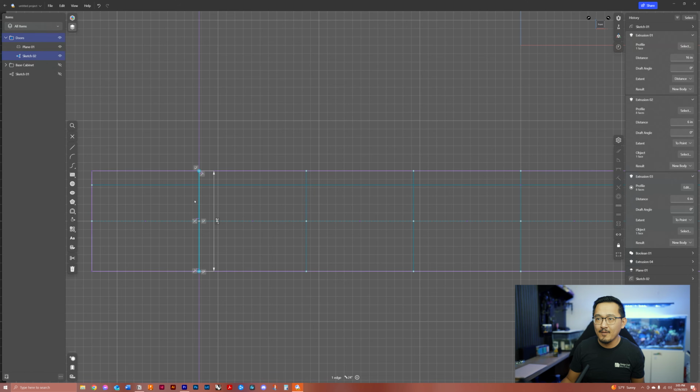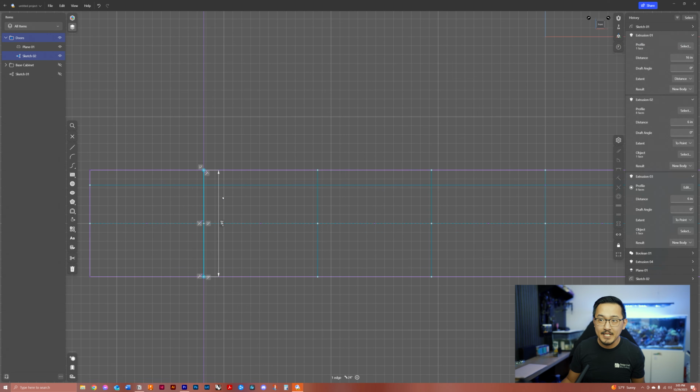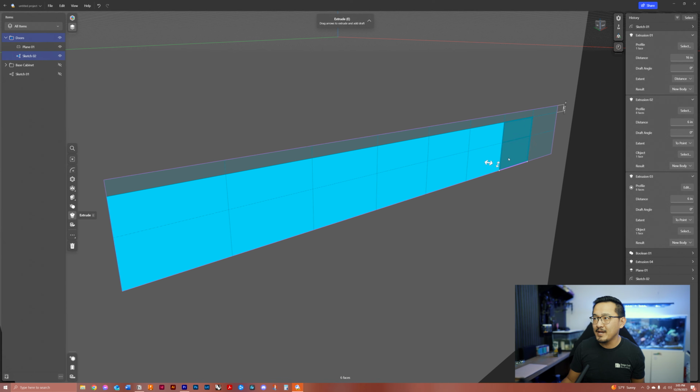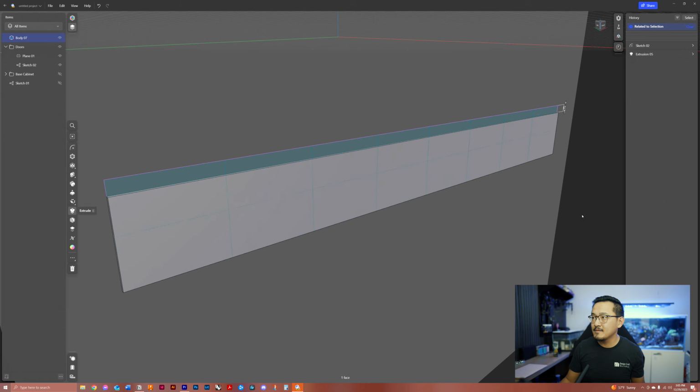Before you guys, I'm going to model out the gaps. We can go in and we can offset these dividing lines 1/32 of an inch on either side to give us a 1/16 of an inch gap. That's going to take too much time. What I'll do is I'm going to extrude the entire panel, and the panel is 3/4 of an inch thick.